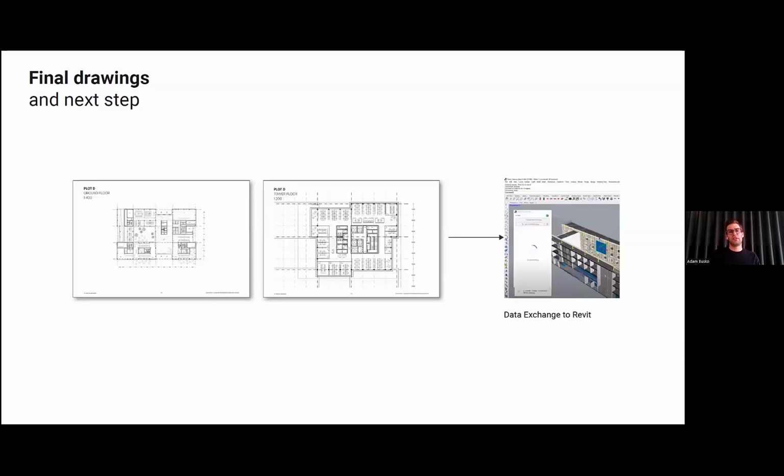And then by the end, most of the drawings we these days also try to produce within Rhino. And like I showed you before, using the template where you have all of your layers with predefined line thicknesses. And now that Rhino, from, I guess, version 8, supports hatches with transparency, you can do most of the things that you would be able to do in Illustrator. We're only waiting for the draw order to be implemented at some point, and then we have everything, right?